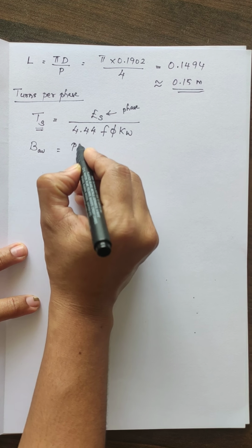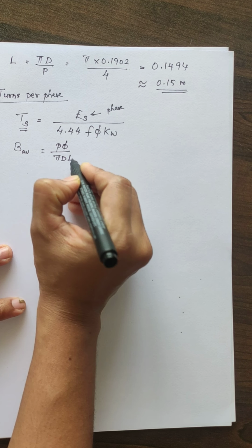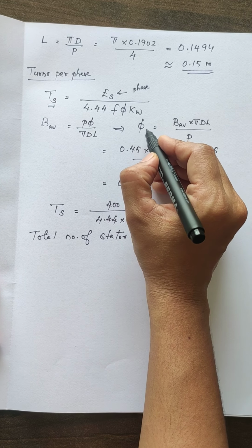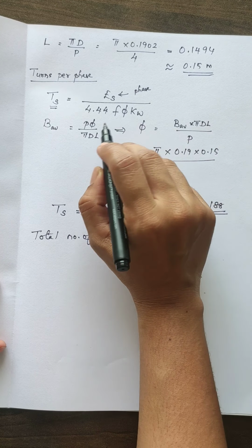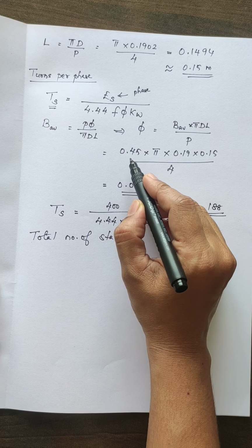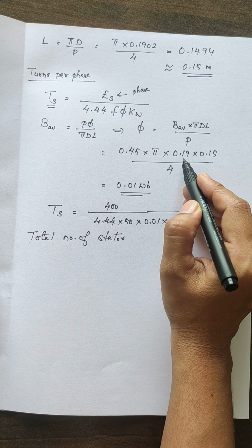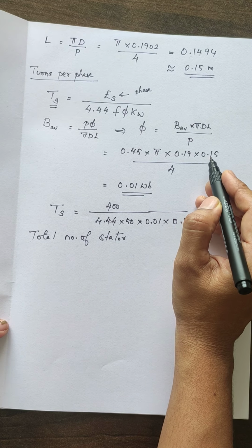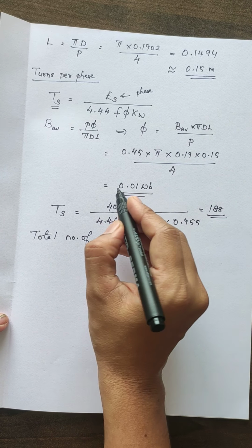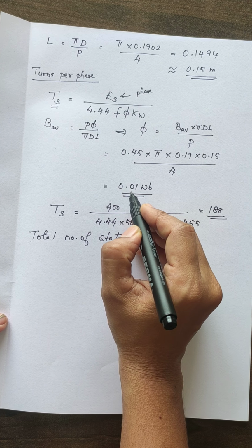So B average is equal to P phi divided by pi dl, which implies phi is equal to B average into pi dl divided by P. So B average is 0.45 into pi into d, which we have got as 0.19, into L, which is 0.15, divided by P. The number of poles is 4, and on solving this we will get the value of phi as 0.01